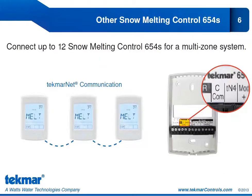The other benefit of having a snowmelt control with tekmarNet communication is that now we can connect multiple snowmelt controls together for a multi-zone snowmelt system. So here in the image we show 3 of the 654s that are connected together through the TN4 and C terminals, but we can have up to 12 654s connected. The maximum is a 12-zone snowmelt system. But it does give us that capability to have a unified control solution with tekmarNet communication for multi-zone systems.